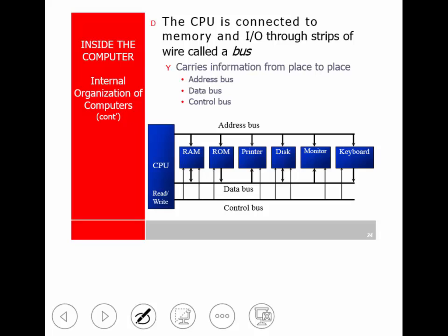Let's say we look at the address bus. It may have the lines A0 through A15. This is 16 lines or wires that connect between there. This is the data bus. This may be D0 through D7, or it may be D0 through D15, D0 through D31, depending on whether it's 8-bit, 16-bit, or that there.